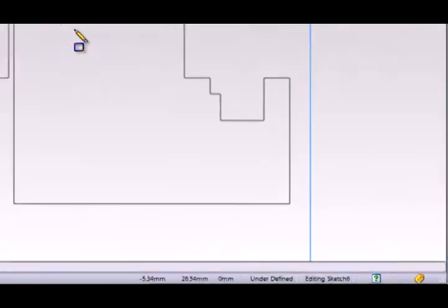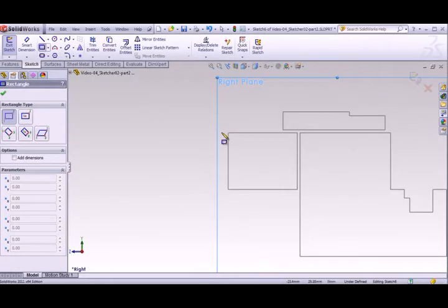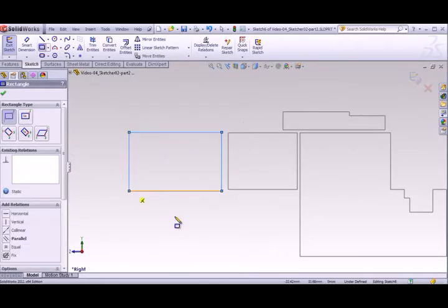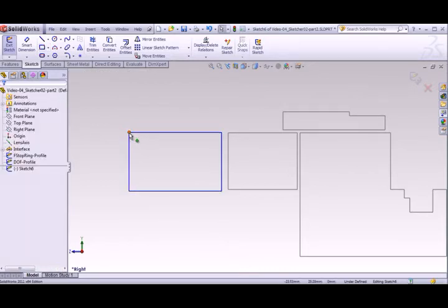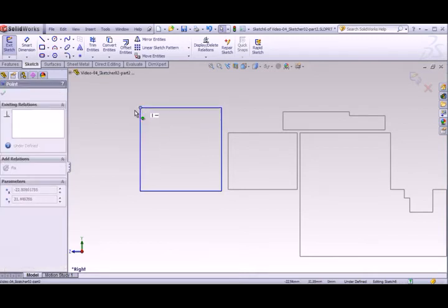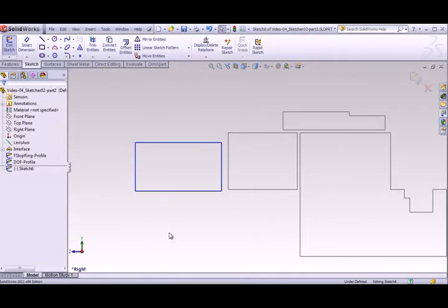So let's go ahead and draw our next rectangle by clicking twice. Now I want to tilt the edge of this rectangle back. I'm going to hit the Escape key to drop the tool. And notice that when I drag the corners of the rectangle, the edges remain rigidly fixed as vertical or horizontal. Even though we can't see them at the moment, the rectangle tool has created some constraints all on its own.